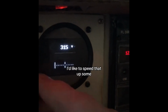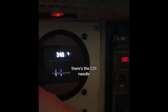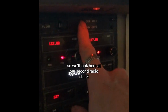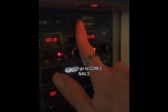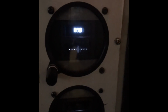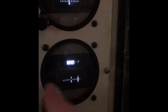This is kind of slow. I'd like to speed that up some. So when I turn it back around here, there's the CDI needle, and pretty soon we'll get a TO flag. We've got the away flag right now. So we'll look here at our second radio stack. So this is our radio selector. This is now on COM1. So we'll go to COM2 NAV2 and we'll check this. See that the CDI does move as I change frequencies.